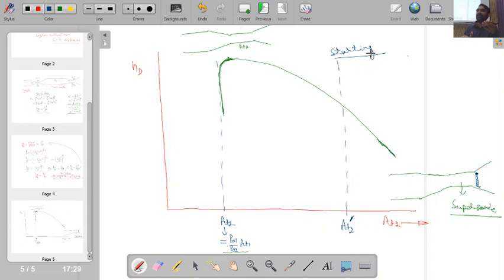Obviously it can start, but starting of the wind tunnel must happen at the desired supersonic flow conditions. If you keep the area less than that, then your normal shock wave will get stuck at the second throat section and it will not pass this section. Okay, so if it is stuck at this section, it will not give you the desired conditions.